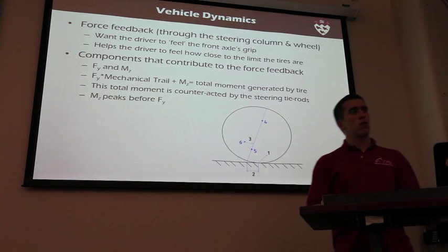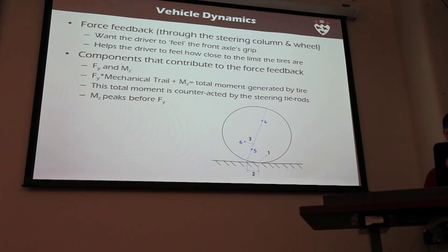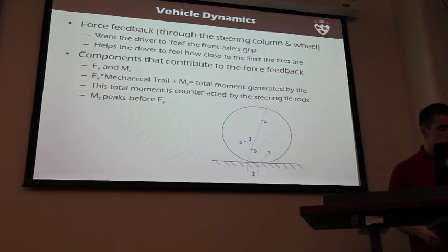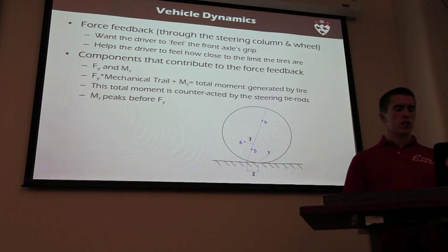So why wouldn't you just have 2 straight points that are forward of your contact patch? This is dependent on other suspension parameters, such as, I guess, anti-dive, how your suspension reacts in other cases, but that's affecting general suspension parameters of the car, but not specifically steering. So are you concerned that the wheels become cambered when you steer?